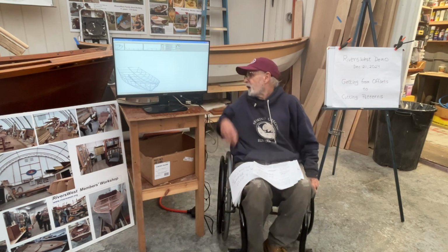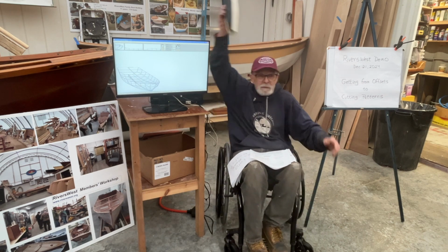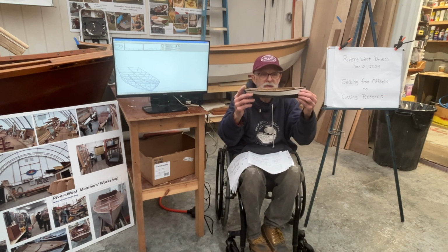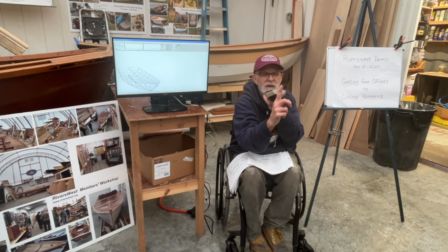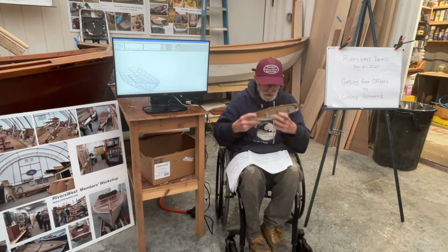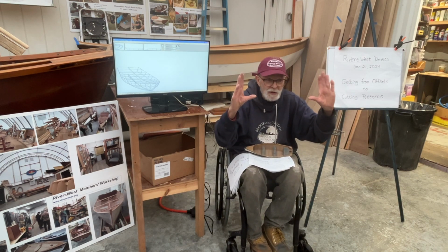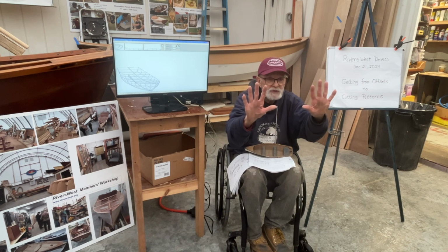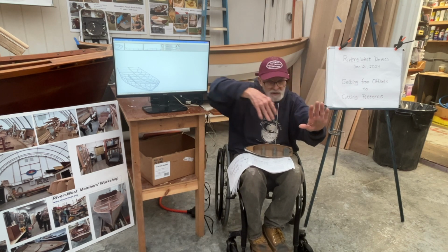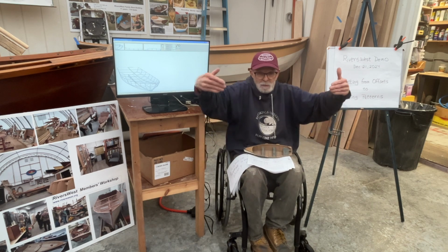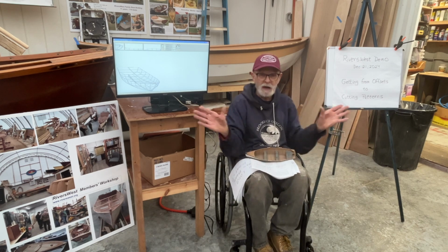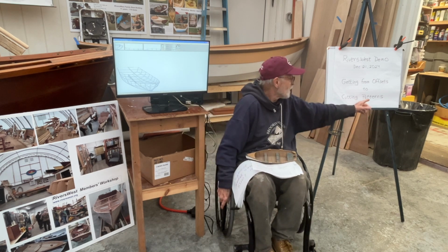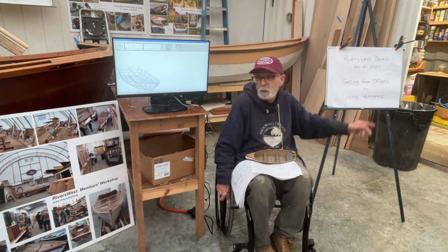And from those two, you can produce a 3D boat. Your side view, they do half view, and they typically do an end view. They only do half of it, and they'll do the other half like that. The table of offsets gives you a two-dimensional picture. But if you think about the side of it, the side's going to be longer, and you need to be able to expand that, so when you lay it out on plywood, you're actually cutting the full-size pattern. And so how do you get to your patterns is basically what you can do.